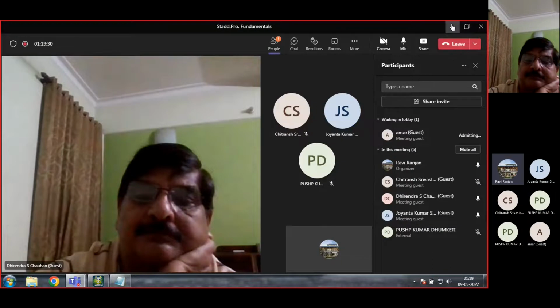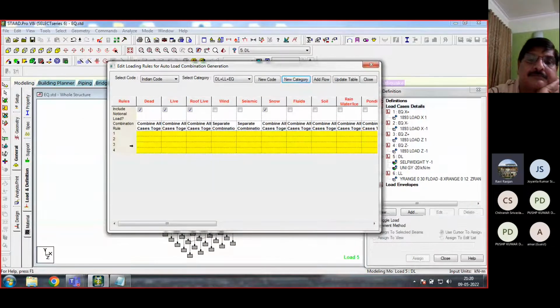Okay, so 4 number of rules. First rule, we have 1.5 for dead and live. So we give 1.5 for dead and 1.5 for live. Then second rule, we have 1.5 for dead and 1.5 for earthquake.